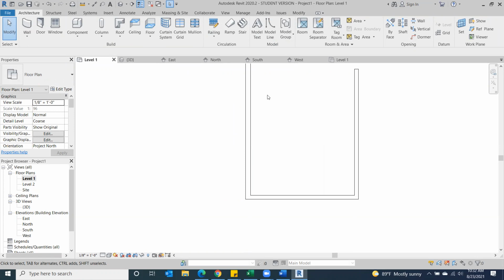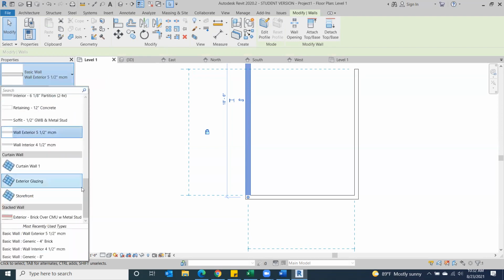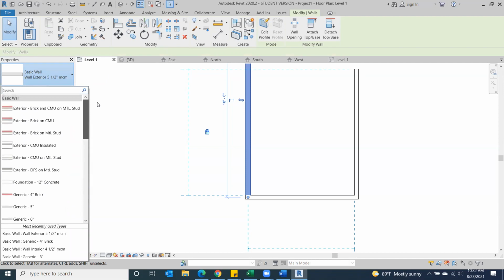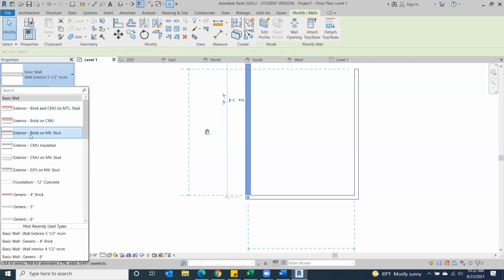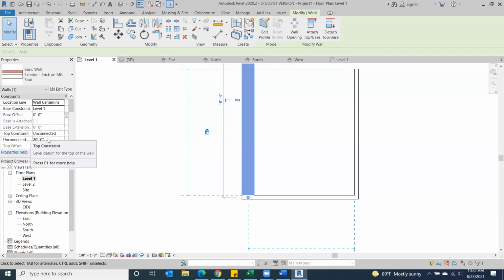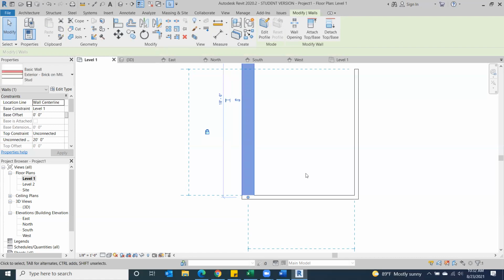All right. You have to actually create your own walls first. Right, so I did that. So I'm trying to edit the wall that I created. Now you picked on this wall right here. Yep. And if we come to our type selector in this area right here and do the drop down, if you pick one of these other walls, the pre-made ones they already have, if I use this brick one, for instance, that's just going to complicate things for you. You don't want to use that.